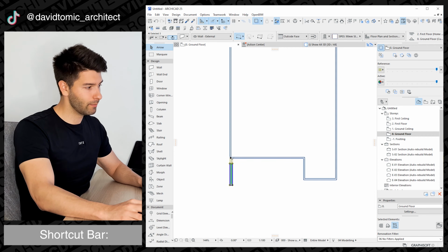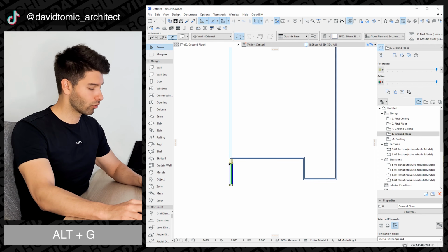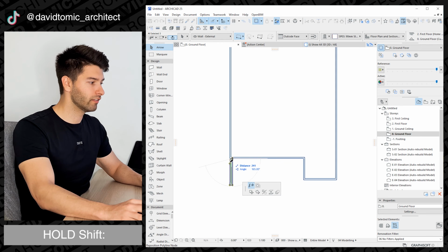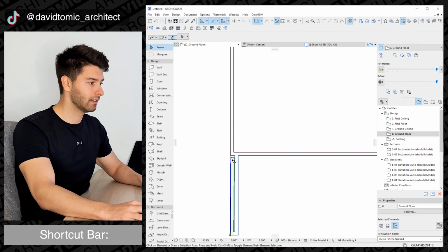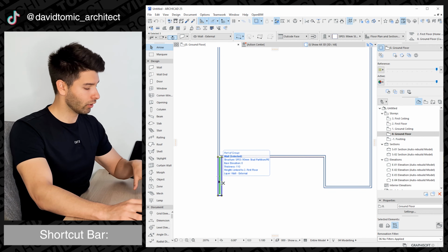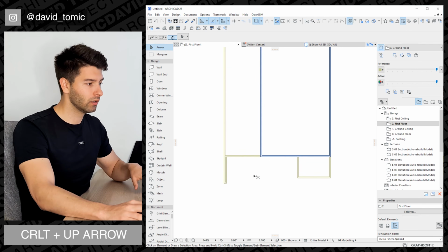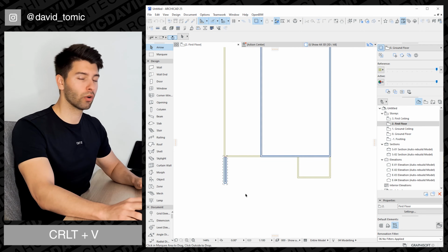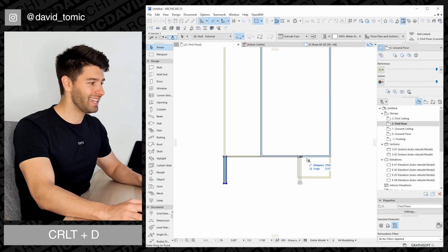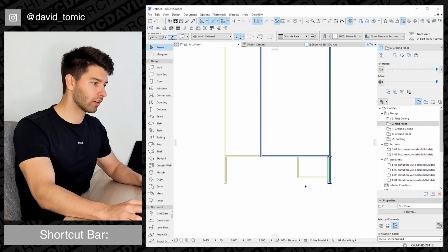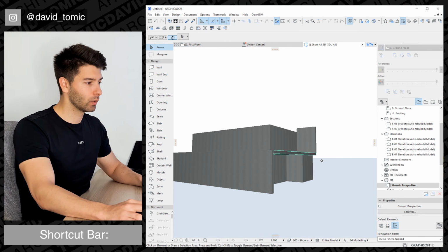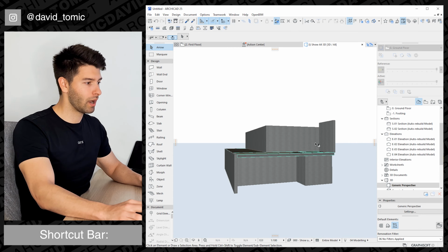And finally, to bring these back in line with this wall, I'm going to ungroup them, Alt G, clicking our Move node and simply holding the Shift button, click once, drag back in line. What I'm going to do now is highlight this bottom blade wall, go Command C, up, and Command V or Control V, depending on what system you're on. Select that, Control D to be able to move it, drag it all the way across and click it on this side.